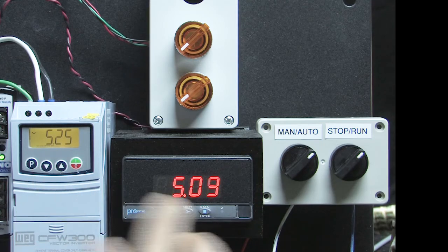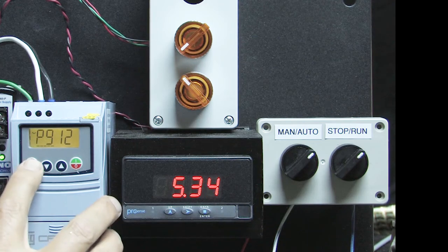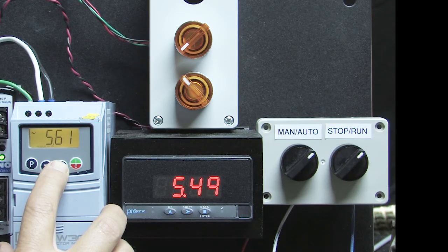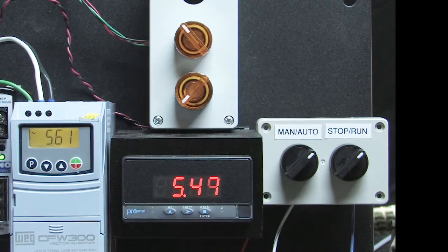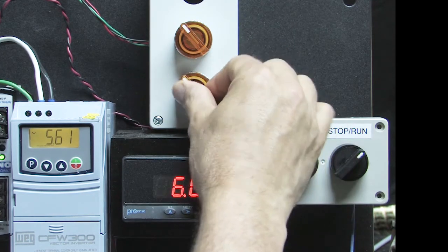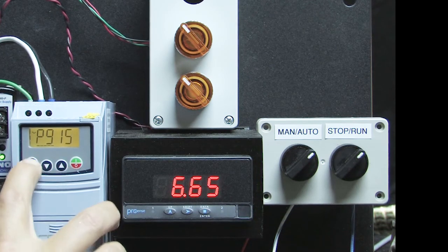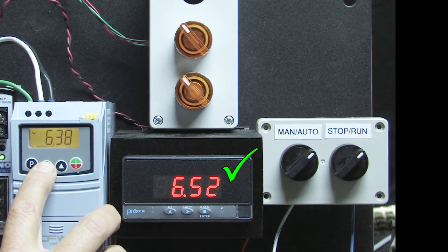Great. Let's turn on digital input 3, and as the system settles out at the new set point, we see it's off a little bit too. So I'll just go to the next table entry and tweak that to get the actual system pressure to 5.5 psi. Of course, if we enable digital input 4 only, we get our 6 psi. And if we enable both digital inputs, we see that the system doesn't settle out at 6.5 psi, so I'll go to that table entry and tweak it a bit until we get 6.5 psi.